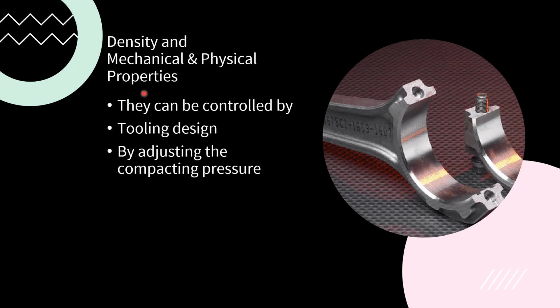Mechanical and physical properties. Density is a physical property. We put it here so you can pay attention to it. You can control them. You can use your tooling design to control them. You can also adjust the compacting pressure.